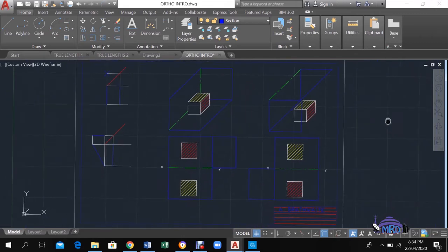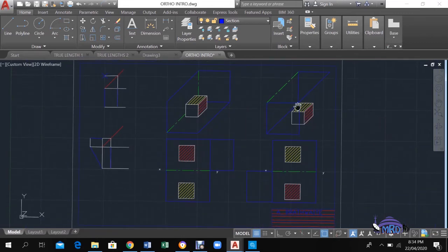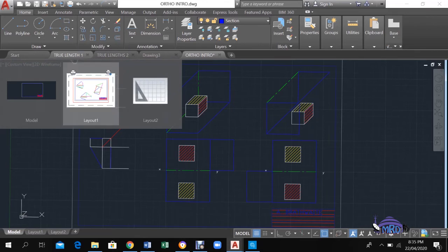You should remember that we had looked at the planes of projection, and we had placed objects in those planes to allow us to understand what first angle and third angle projection representations were. And you should also remember that we had placed the XY line, which we refer to as that hinge line, to allow us to transfer measurements if we needed to, or make references if we needed to. The XY line provided that opportunity. So let's get right into the true lengths then.